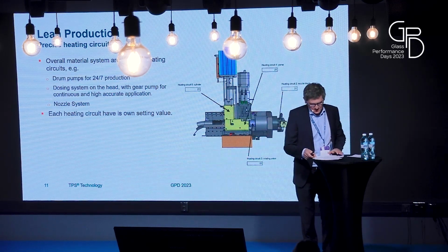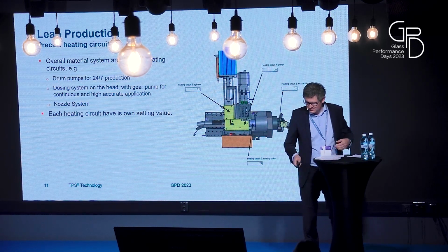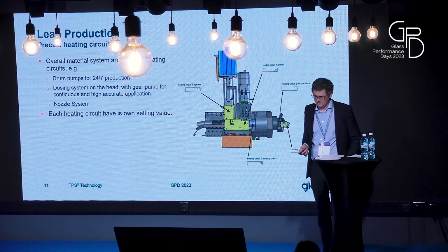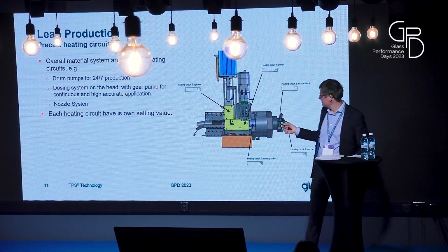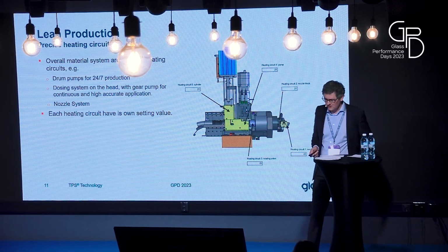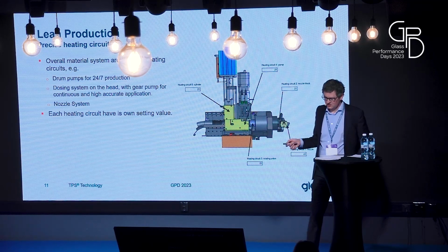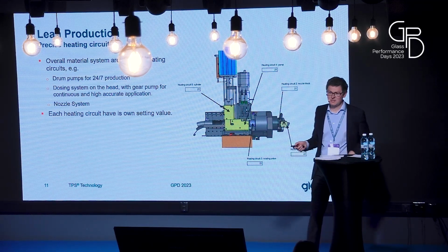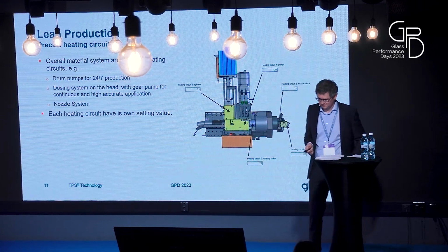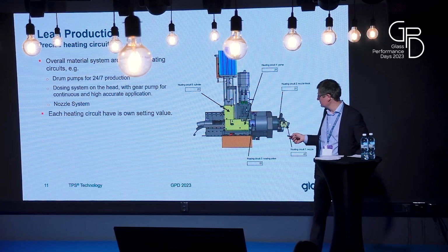I have mentioned that the temperature is very important, and this is why there are different heating circuits in the technology. There is one for the drum pumps for a 24-hour production, a further one for the dosing system, and in addition, a further one for the nozzles. And sometimes it's necessary to adjust them to the right environment temperatures, to the right environment settings. So you should have the opportunity to do that.